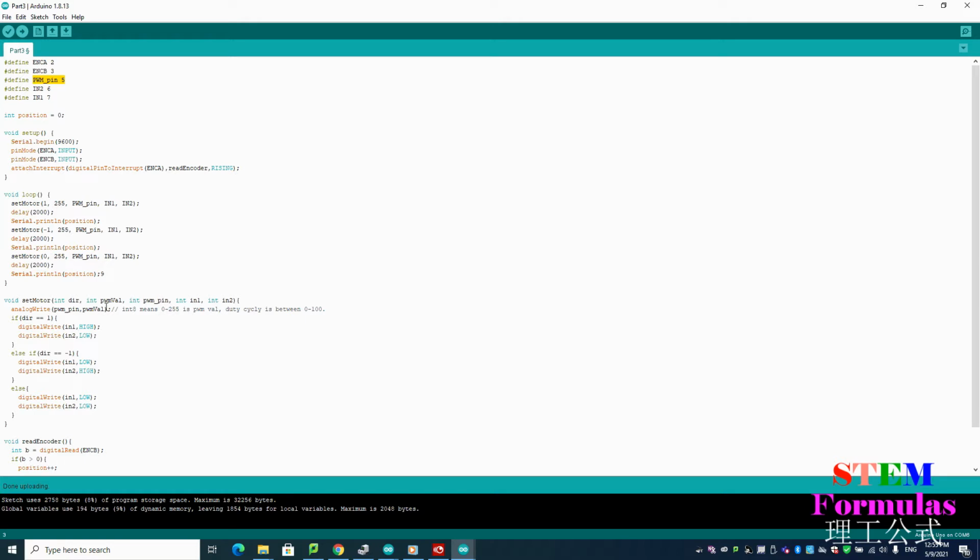So it knows how to follow this. You've got to say which pin you're talking to and essentially the PWM val, which you're determining here. One thing to note is that this is an int 8, so this means that it's going to be a value between 0 and 255.